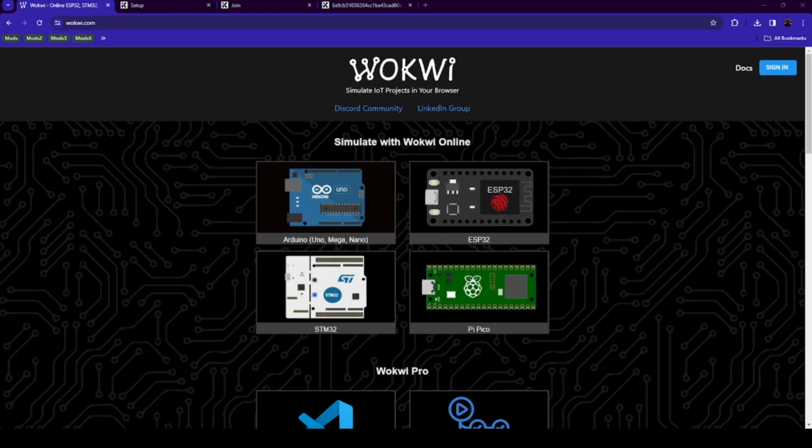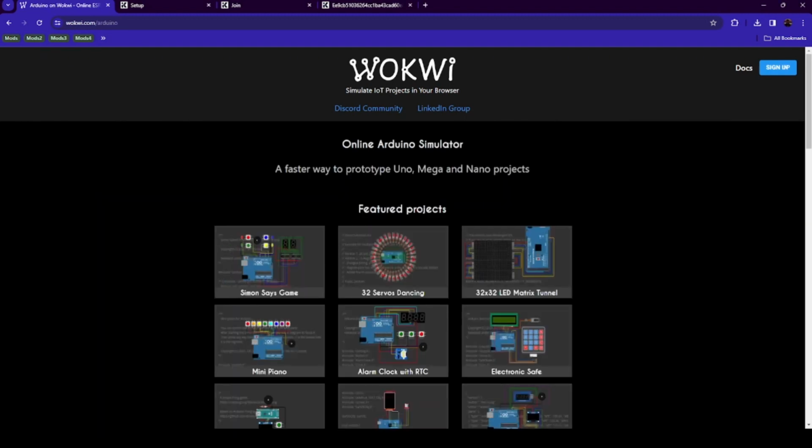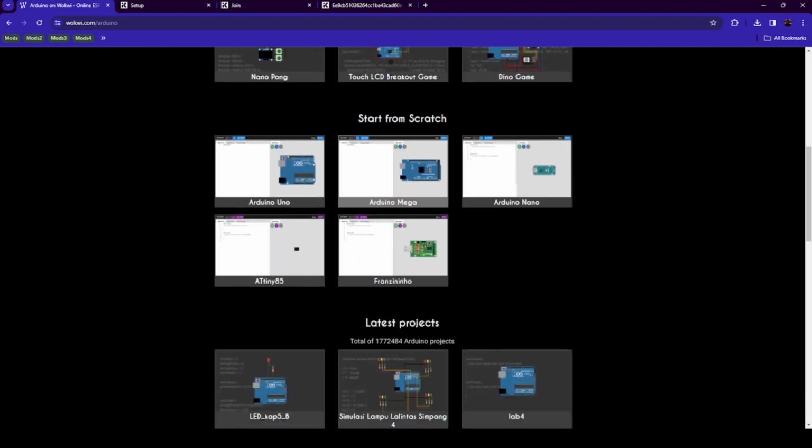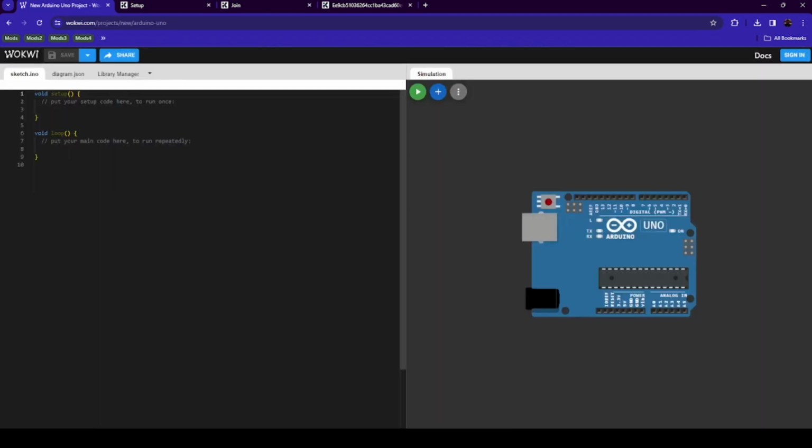Hello, I am here to demonstrate how to use WOKWI Arduino Online Simulator. So first we go to WOKWI.com, which you already have here, and then we choose Arduino. From here we scroll down and choose the Arduino Uno, which will be the one we use for our microcontroller course.